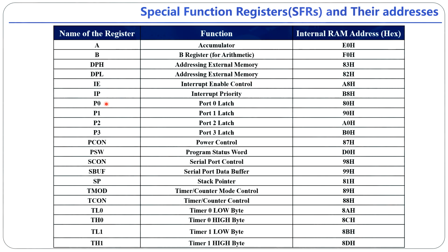That is the IE register name. The function of this register is interrupt enable control. The location of this register is A8H. Next register is the IP register.